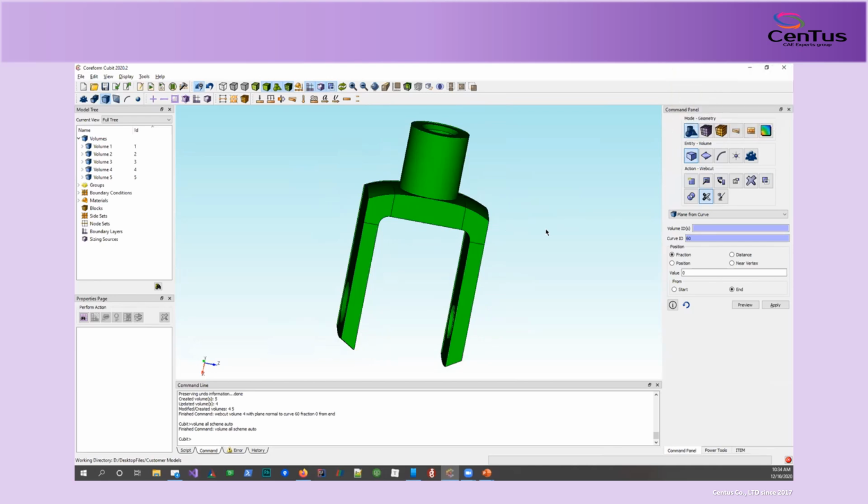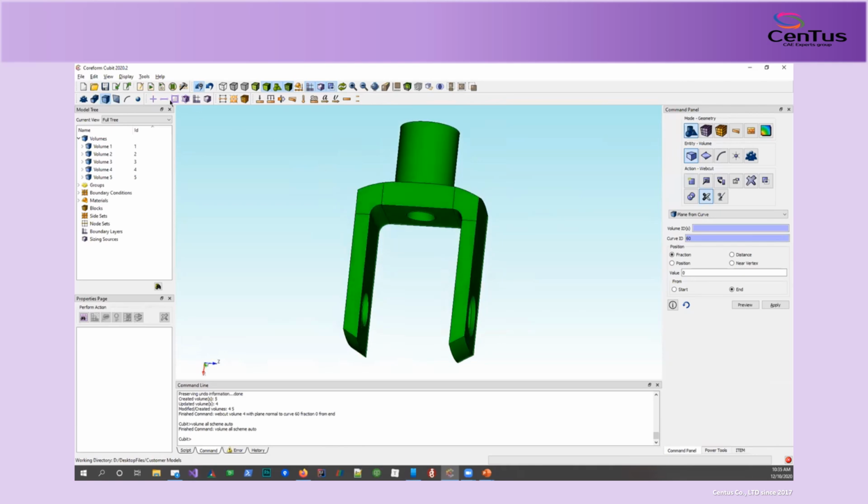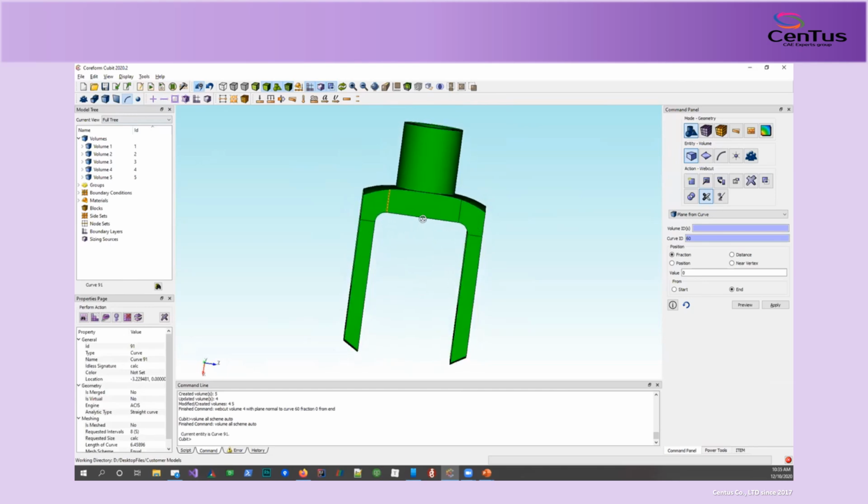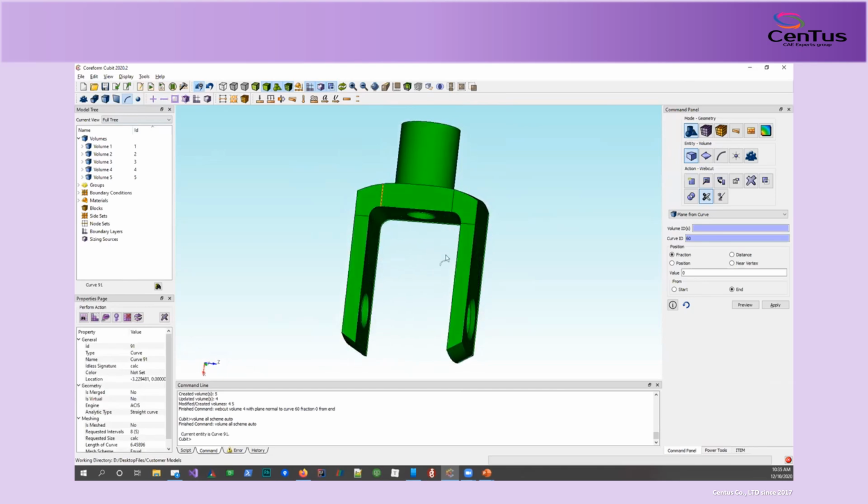So imprint essentially takes the image of the curve of the surfaces and maps those across the boundaries. So if I have 2 surfaces that have features that overlap, imprint will map all of those surfaces onto the same surface. In this case, they're really simple because there's only boundary curves. We don't have any internal curves in this, which is a good thing. It makes life simpler. In general, when you're trying to do these web cuts, look for cuts that will create mapped, or what we call submappable, which are rectangular surfaces that are kind of combined together. Imagine taking a cardboard box and unfolding it. All of those pieces individually are mappable, so the whole thing is submappable. So you want to make cuts that will do that.